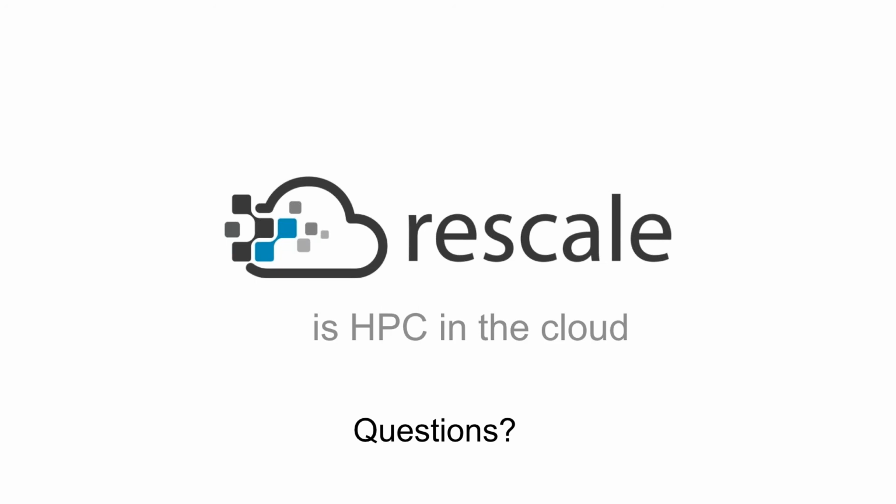So what I was showing in those slides on the harmonic before is that with this harmonic solver we've developed, we're only focusing on blade passing frequencies. And so we're losing other things, which are normally of lesser importance. And you can just solve in 2, 3, 4 times the time, which is not that much. It's more time, but it's affordable, and it gives you a solution that is physically closer to reality.